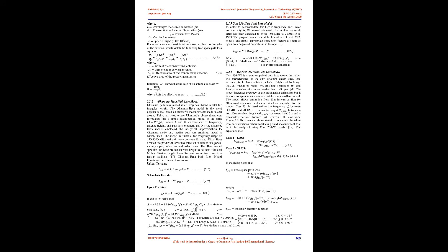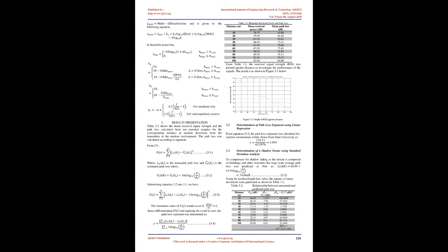2.1 Test bed setup. The test bed consisted of a Wi-Fi radio, GPS receiver, a laptop, pen, and recording book. The received signal strength, RSS, on the Wi-Fi interface was detected by the inSSIDer software running on the laptop, and the measured signal strength was recorded at random positions of equal distance, increased at intervals of 10 m from the transmitter location. The 2.4 GHz access point was set up at a fixed position at a 5 m height